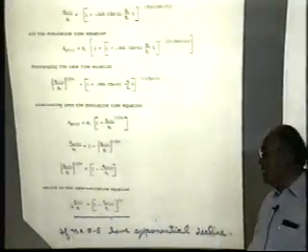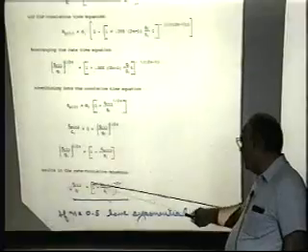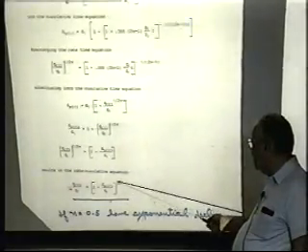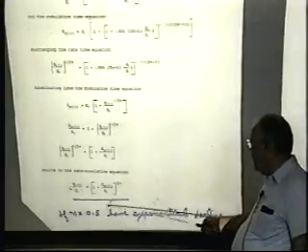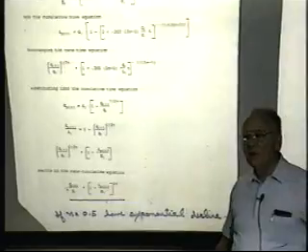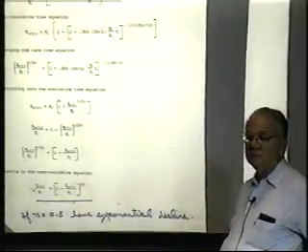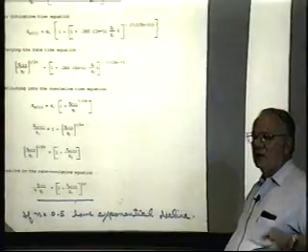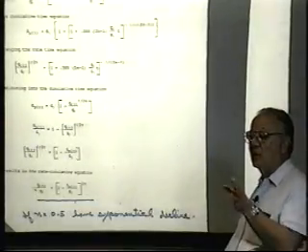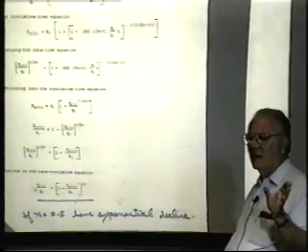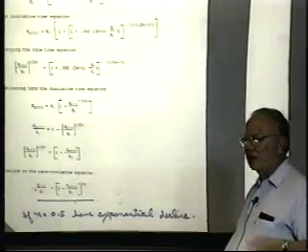The way it's used by the average engineer is you plot it and you get a straight line, you do an extrapolation. They're making the assumption, well, they don't realize that the slope of the back pressure curve is a half, or it's exponential. So if you're doing a rate time plot and a cum time plot, and you're getting different answers, you should be getting the same answer if you're doing it right.